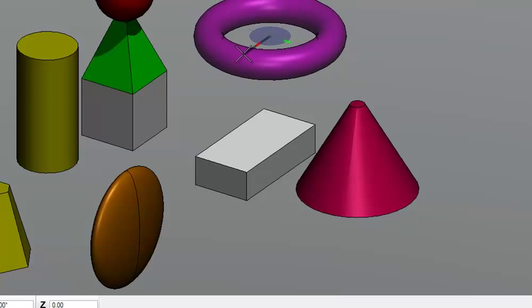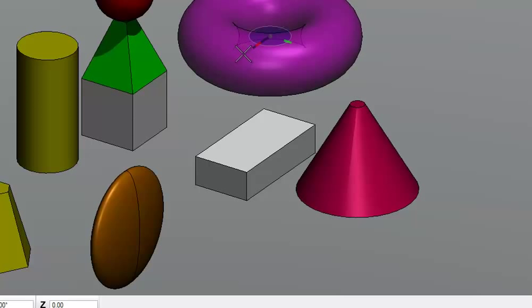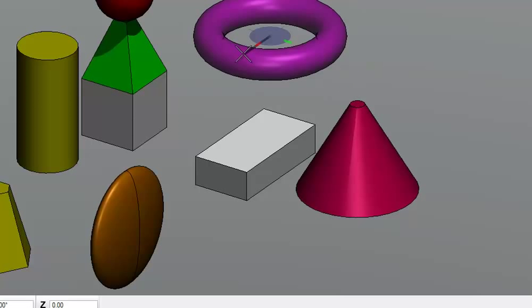And a secondary radius, which would be 1.5. And there you have a torus. So it's the center point of the actual tube itself, the center point of the object, and then a secondary radius to give you the radius of the tubular shape. And we're just doing primitives. We also have extrusions and all kinds of things that we can work with and play around with.